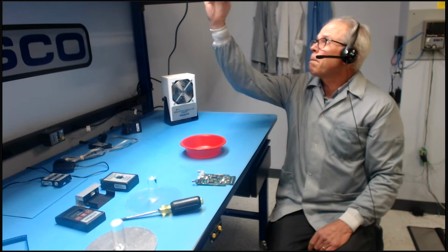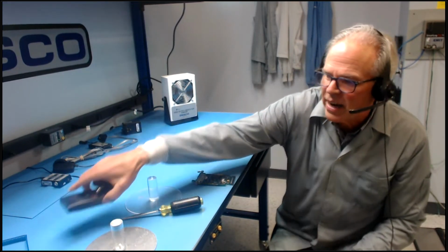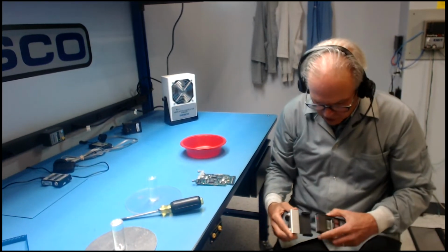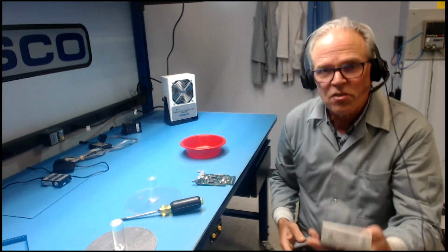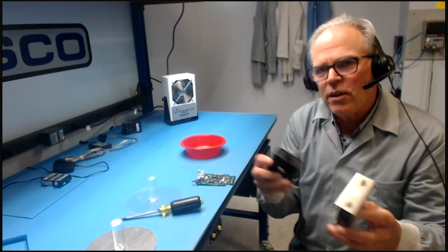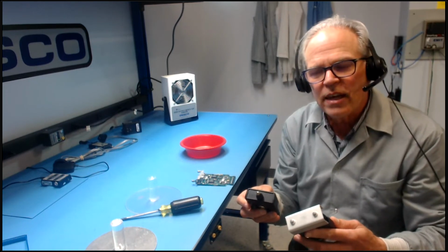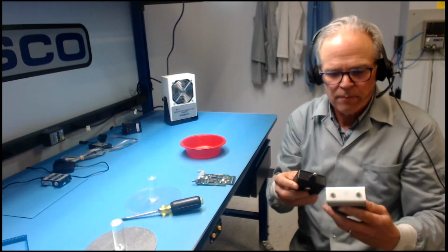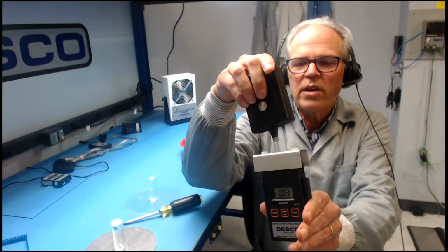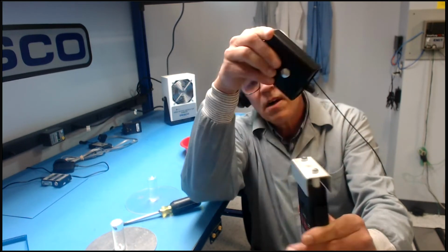So the general way that ionizers get tested, and you're not going to be able to see the actual dial of this very well, but I've got this field meter and a charging plate. The way that you test how fast an ionizer is working is how long it takes to decay 1,000 volts to 100. So let's see, I'm not sure if you can see that. Okay, so I'm going to put a charge on there. It's almost 1,000.